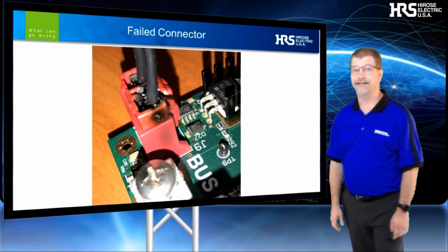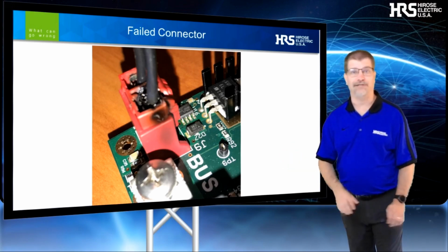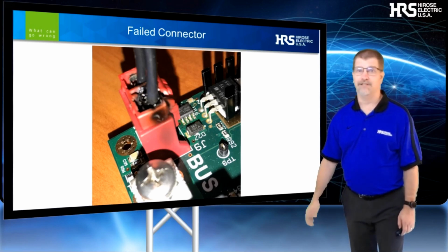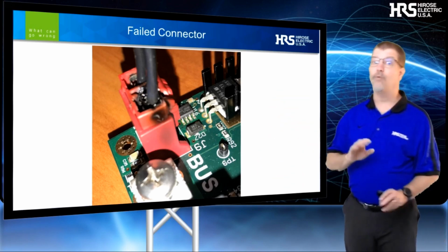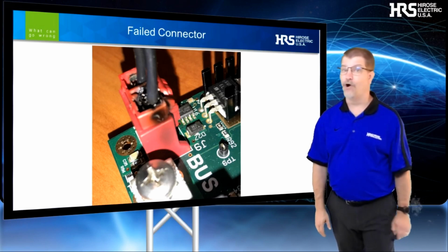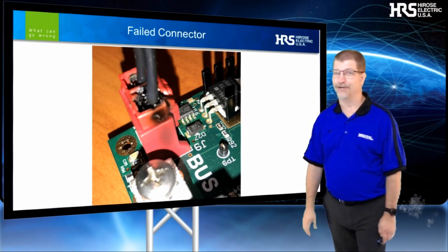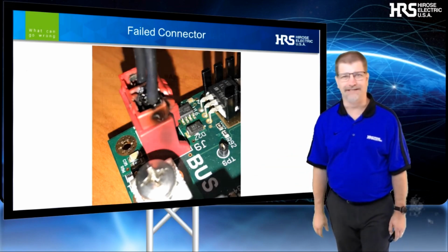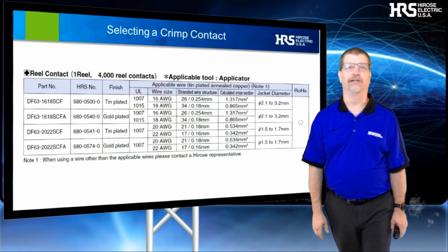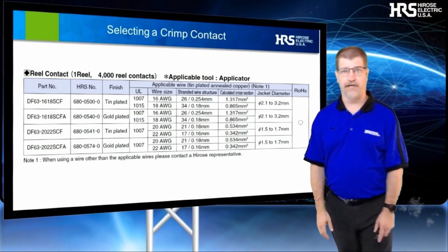The insulation thickness, diameter, and material can be critical to getting the right results from your crimp. This burned out connector was a result of the wrong wire gauge, incorrect insulation thickness, and a poor crimp, all combined together. These three things could have resulted in a fire. As you can see in this picture, it wasn't very good. So choose wisely.